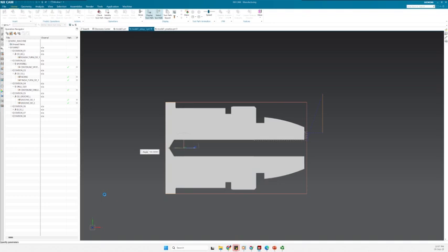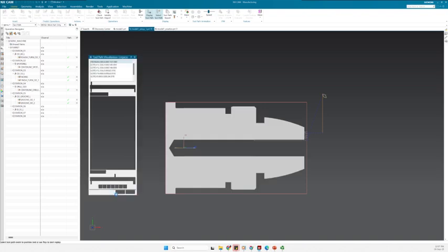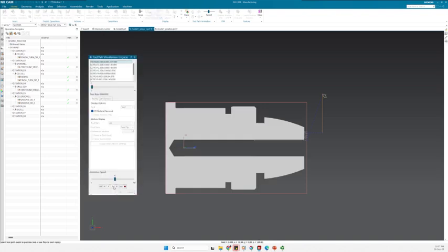So I don't repeat it anymore, but of course the spindle values, the movements, the parameters and even the number of passes are something that needs to be checked. But now we just go for the default settings, but definitely you need to check those with your specific program that you are making for your assignment.